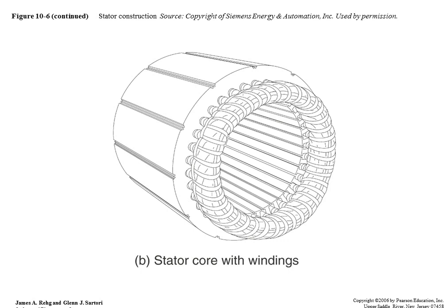You do all the windings, dip and bake it in one case, and the baking is being done at about 500 degrees. When they wind, the coppers have a tendency of touching, but how do you keep them separated? Yeah. The issue is, why do you care?